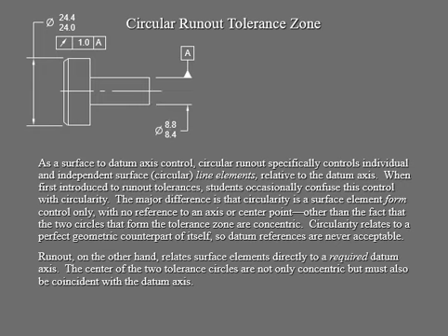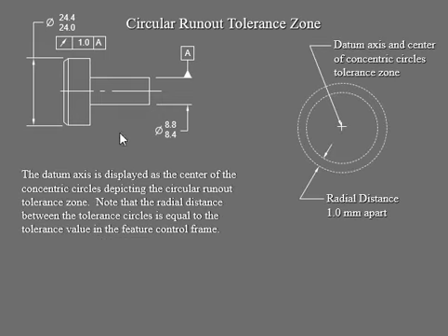Your diameter is 8.4 all the way to 8.8, right here. Since you have 2 circles, one is right there and the other one is right here, 2 diameters, therefore 2 circles. So they're not concentric, but again, you have a coaxial, meaning you have the same datum axis. We already know that, we have been looking at it again and again.